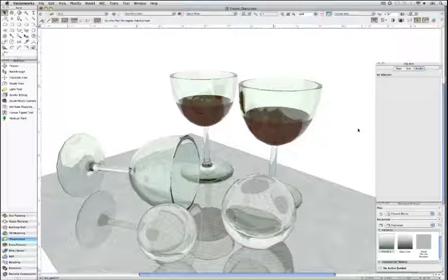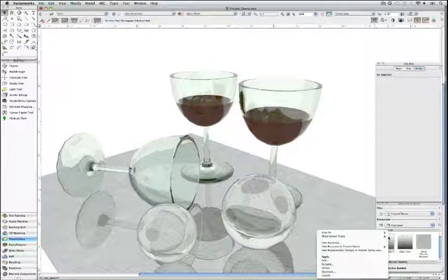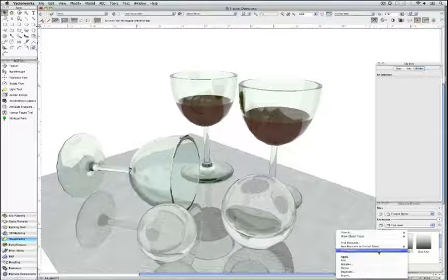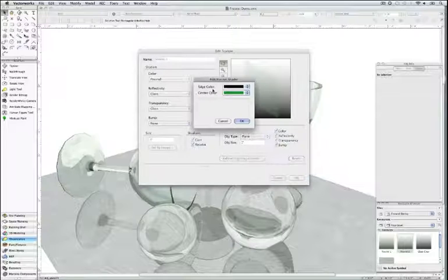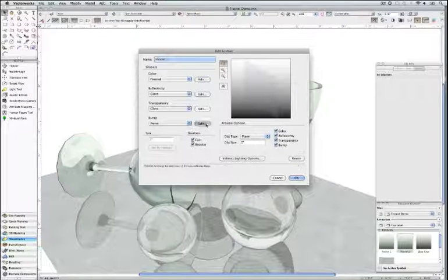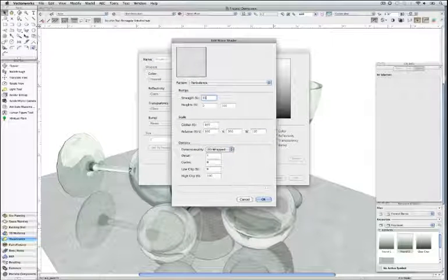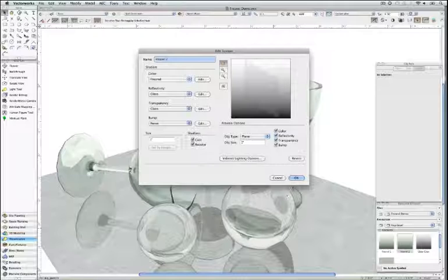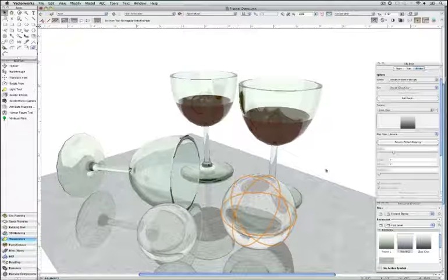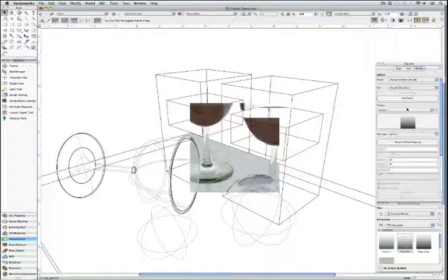Now let's duplicate that texture once again. We'll pick a catchy name like Fresnel 2 and we'll edit it, first for color, changing it to blue, and next we'll add some bump, as this texture might simulate ice. Now we'll apply that texture to the one sphere here on the right and render it up so we can see what it looks like.